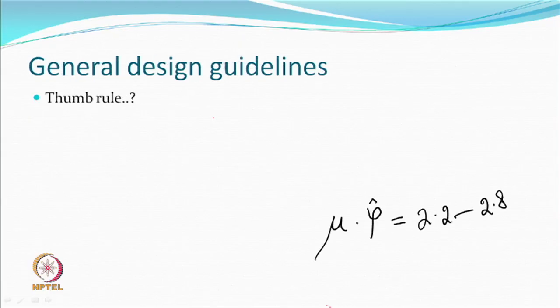How do we decide what will be the wrap angle and twister angle? You have some guideline. The twister angle could be equal to helix angle, because you know the denier of the yarn and therefore you know approximately what twist is there. So, you have some idea and you can say, well, this is it. But what it means is every machine is going to have one twister for one type of yarn, which will be difficult. They will have a range. So, there is a possibility that you may not have achieved 0 value, but you would have come very near to 0.